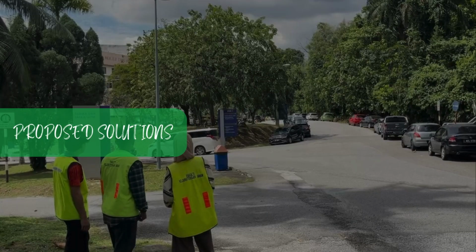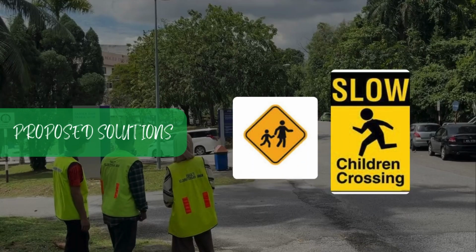Next, we can introduce a reduced speed limit sign. JKR recommends a lower speed limit of around 30 km per hour in school zones. This sign should be placed along the downhill section and repeated when necessary to remind drivers to control their speed, especially on a slope where it's easy to go faster without realizing it.